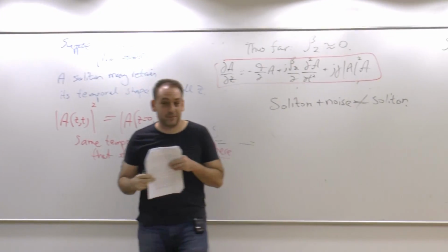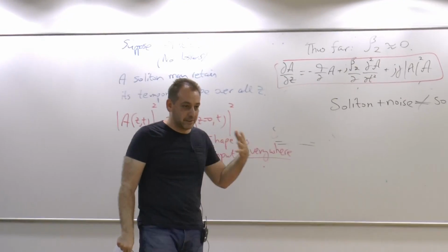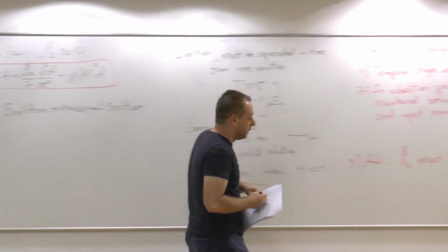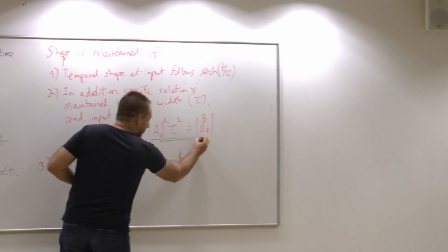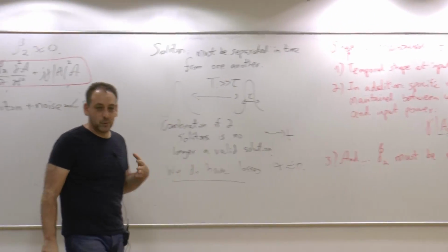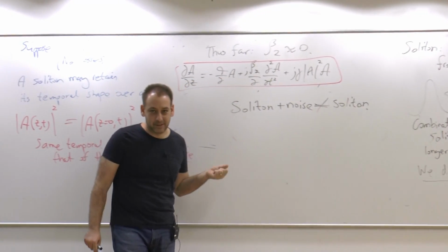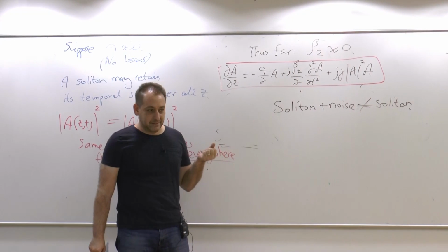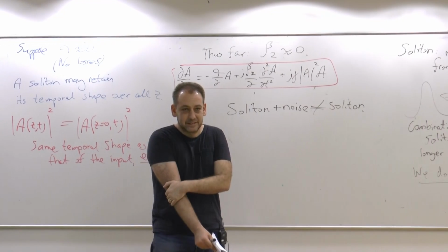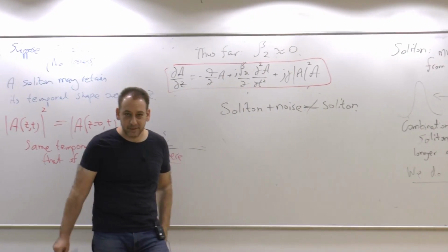So if we try to amplify these waveforms, even very gently, to take out losses, so on average we have not taken out power at all, then yes, we may be able to retain this relation at the cost of noise. And this noise will accumulate, and in the end of the line will break the soliton apart. This can survive over hundreds and even thousands of kilometers of fiber, but sooner or later the balance will be broken.